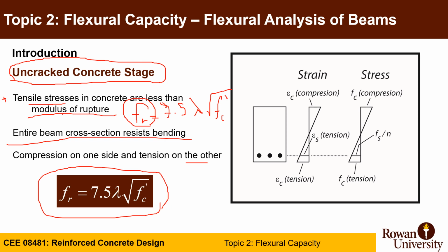On the right side of the slide, you have a concrete section reinforced with rebar, and you can see here we are drawing the stress diagram. It's very similar to structural steel before yielding. You'll have the extreme fiber in compression with its corresponding strain, and the extreme fiber in tension with its corresponding strain. You have a straight, linear relationship, and at the level of the reinforcement, you can also get right away the strain in the reinforcing steel, epsilon s.